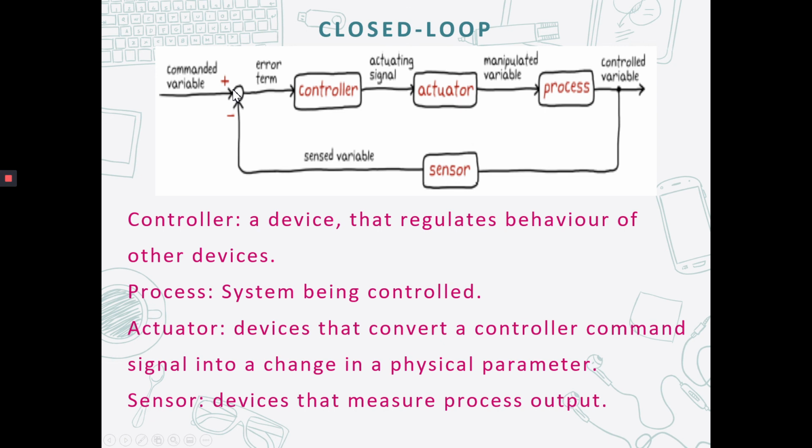If there is any difference between the two responses, the system drives the plant via the actuating signal to make a correction. If there is no difference at the summing junction, the system does not drive the plant, since the plant's response is already the desired response. So that describes the closed loop system.